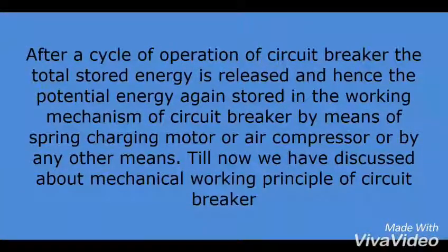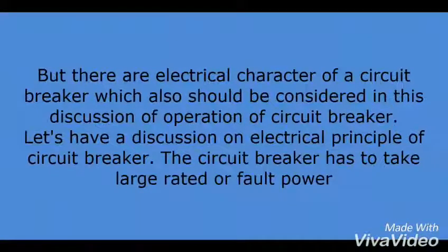After a cycle of operation of circuit breaker the total stored energy is released, and hence the potential energy is again stored in the working mechanism of circuit breaker by means of a spring charging motor or air compressor or by any other means. Till now we have discussed the mechanical working principle of circuit breaker. But there are electrical characteristics of a circuit breaker which also should be considered in this discussion of operation of circuit breaker. Let's have a discussion on electrical principle of circuit breaker.